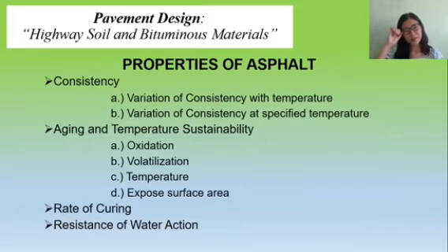So now let's proceed to the properties of asphalt. The properties of asphalt materials pertinent to pavement construction can be classified into four major categories. We have the consistency, the aging and temperature susceptibility, the rate of curing, and the resistance to water action. So the consistency